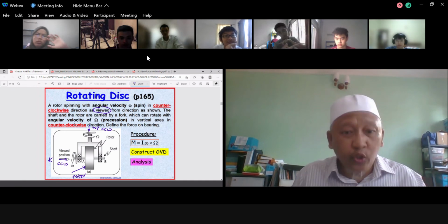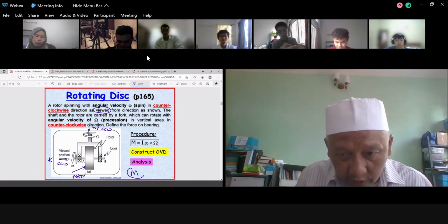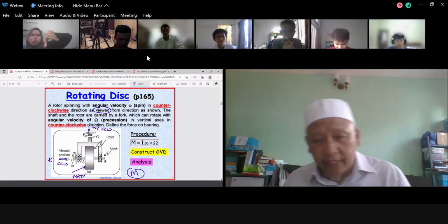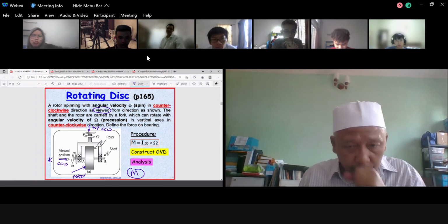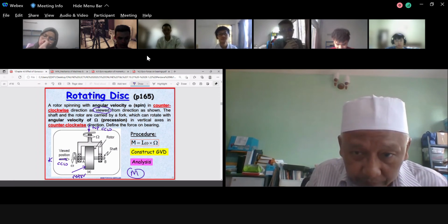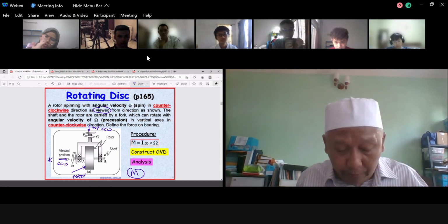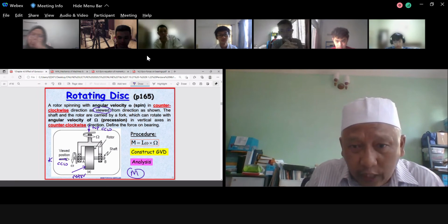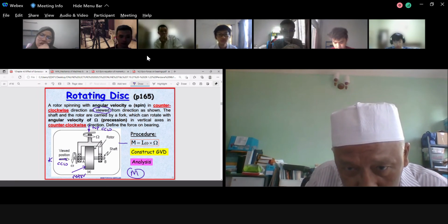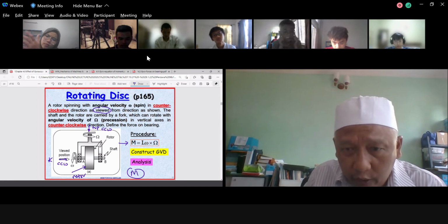So our aim now is to define the M couple. Okay, let's try to define now what is the M couple. This is the procedure, based on my experience solving this type of problem. You start with the M couple, even if the question doesn't ask for it. M equals I omega, the spin, times the precession.